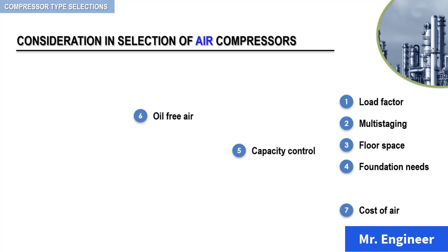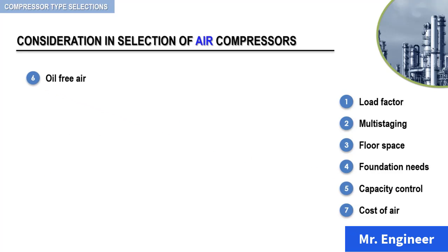The next factor is oil-free air. Here, any requirement for air completely free of oil will rule out any design that operates with oil. This is a criterion to pay attention to, especially if your compressor will be used for instrument air supply.